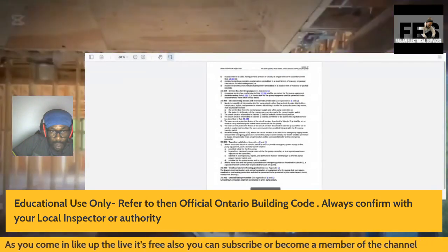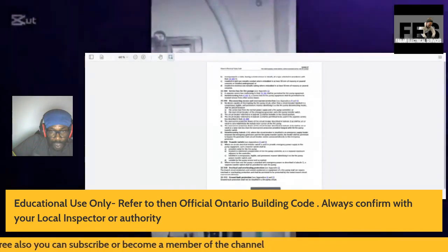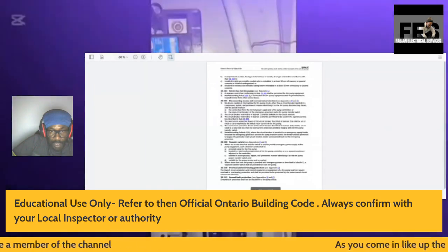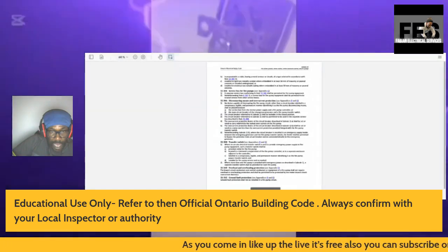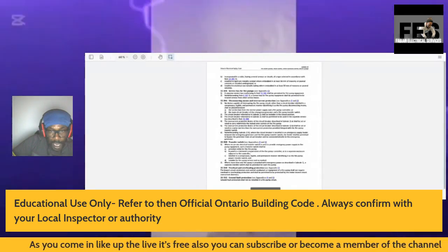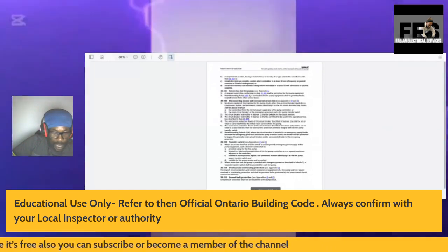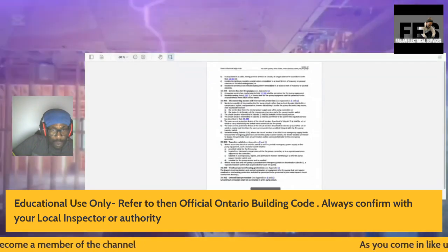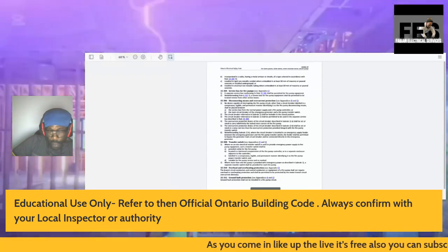Notwithstanding Subrule 1B, where the circuit breaker is installed in an emergency supply feeder between the emergency generator and the fire pump transfer switch, the feeder shall be permitted to bypass the generator main circuit breaker and be connected directly to the emergency generator. So again, this is the transfer switch rule when it comes to the emergency generators and stuff.